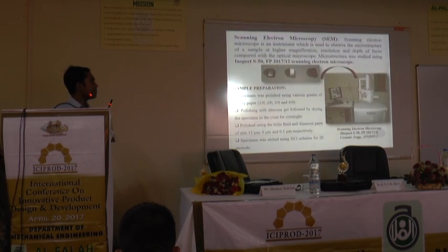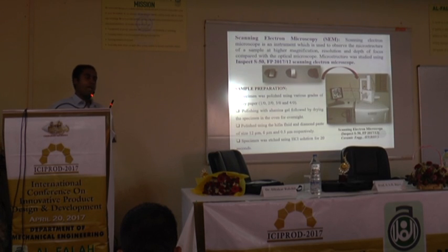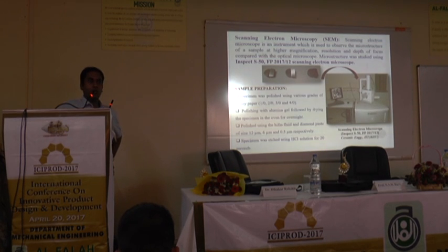Next slide. This is the standard term microscopy. When we talk about the microscopy, then microscopy itself talks about the microstructure. So, suppose we want to determine the microstructure of any material. That means what is the distribution of the grain, what is the morphology of the grain, how is the variation of the material or other factors. So for that we have to use this particular technique. By using scanning electron microscopy, or before using scanning electron microscopy, we have to polish the specimen.